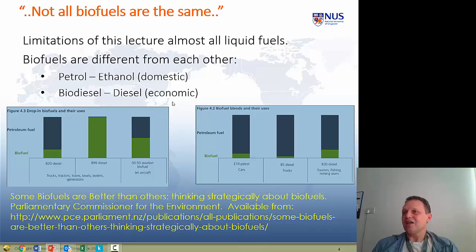If you've got an ocean-going oil tanker, you can almost burn old socks in those engines. Not literally, obviously, but those big diesel engines are very robust and can take very poor quality fuel. If you've got a more modern car though, if you try to put ethanol into it, it'll work, but you'll find your fuel lines corrode.